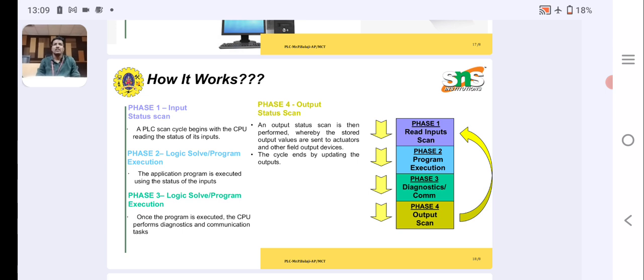Initially, the PLC continues running through the programming and updating the result from the input signals. Each loop is termed a cycle. The PLC operates with each input being examined as it occurs in the program, and its effect on the program determined, and the output correspondingly changed. This mode of operation is termed continuous updating.